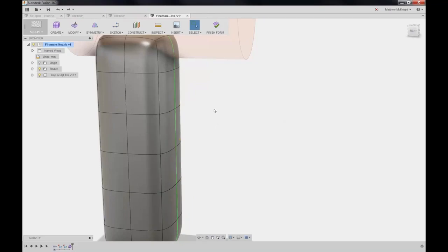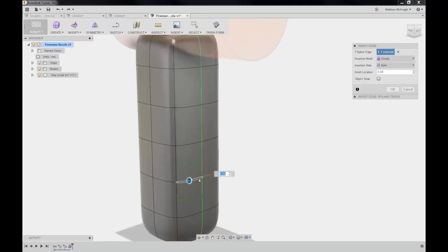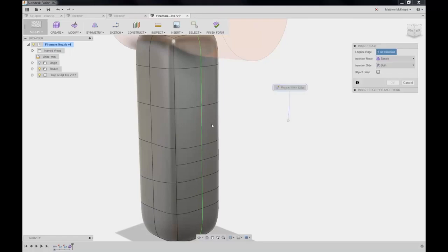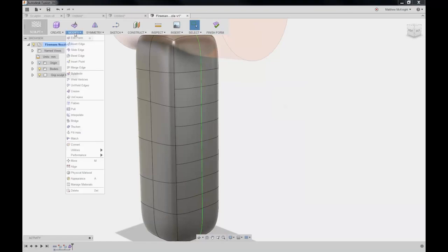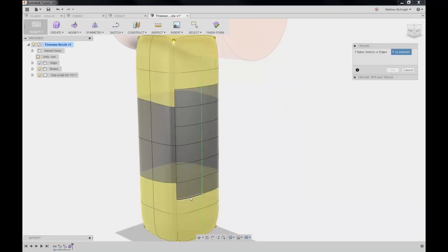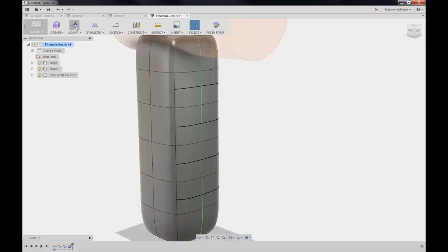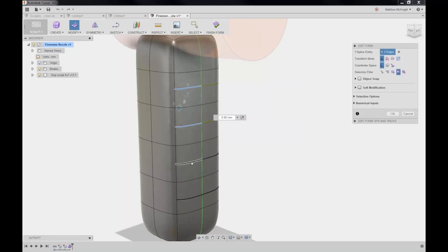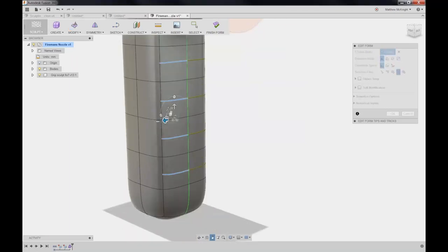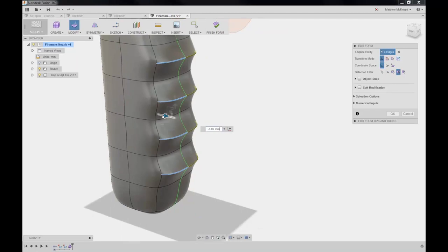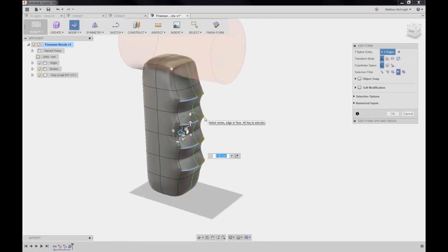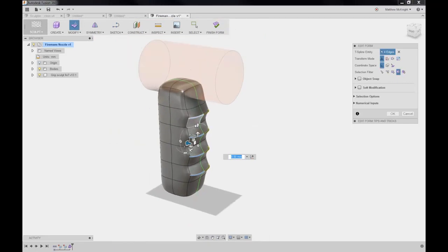So what we're going to do is, like we saw then, let's add those additional edges in place. So we'll grab that one, go OK, let's repeat it, that one, OK, and let's add the crease. Where are we? Want one. So 1, 2, 3, 4. Okay. Drag those out a little bit. I'm holding down the Control key to group select entities in that case, and drag these out in space. And you can see here that we've got now nice defined finger holds for our nozzle.